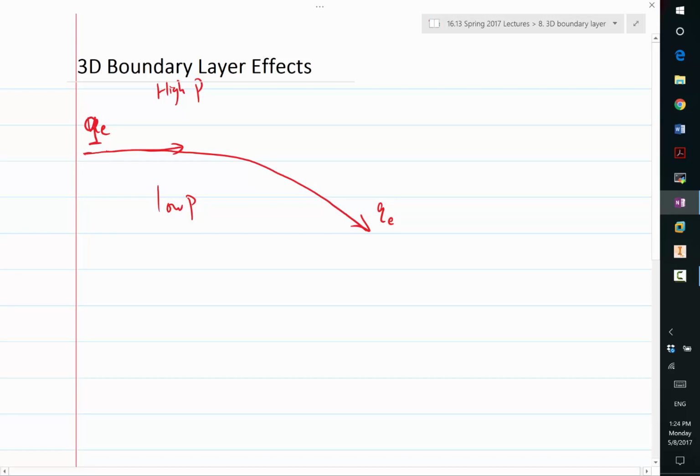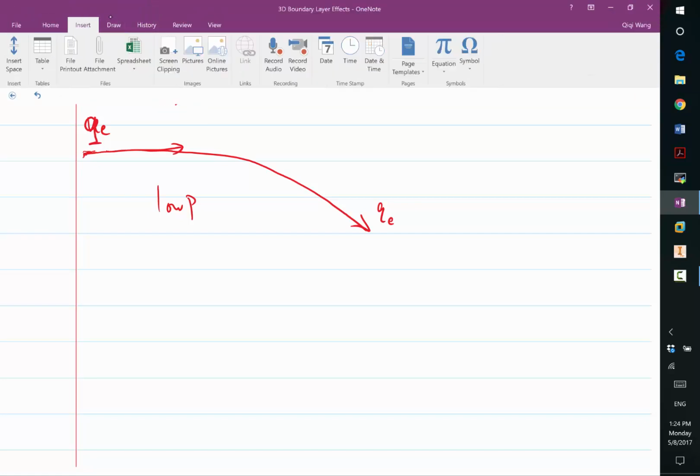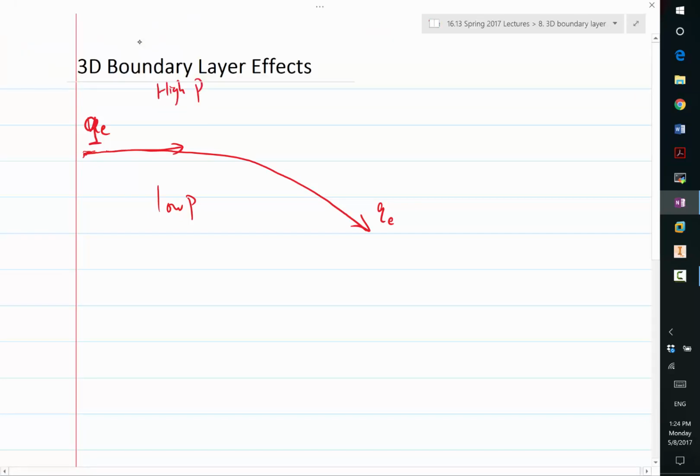Now suppose you have a boundary layer that is exactly two-dimensional upstream. How do you think the velocity inside the boundary layer is going to respond to this pressure gradient? So let's say I want to use the blue to draw the velocity inside the boundary layer. How is that streamline that is inside the boundary layer going to respond to the same pressure gradient? More. It responds more. And why is that? Lower inertia. It has lower velocity or lower inertia, exactly.